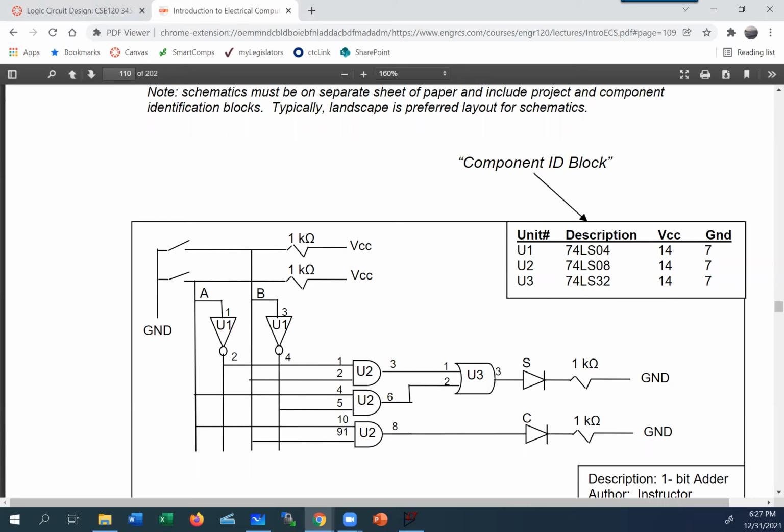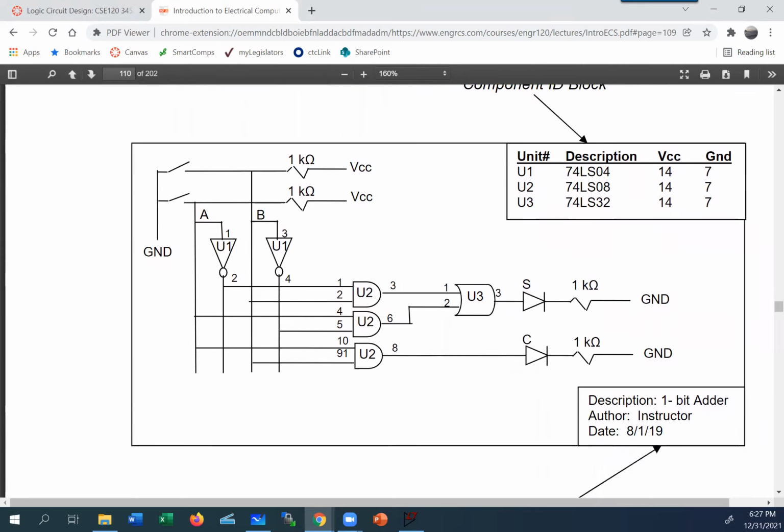And then I typically like to also invert them. So I have a value for the input A from the switch, and at the same time, I also have A not. All I simply do is run it through a NOT gate. B, I run through a NOT gate, and I have B not. Now, whether I need A or B, I've got it all available here. And when I'm doing C, if you remember, the C equation was the only time this would happen is A true, B true. So we'll take A and B, run it to an AND gate.